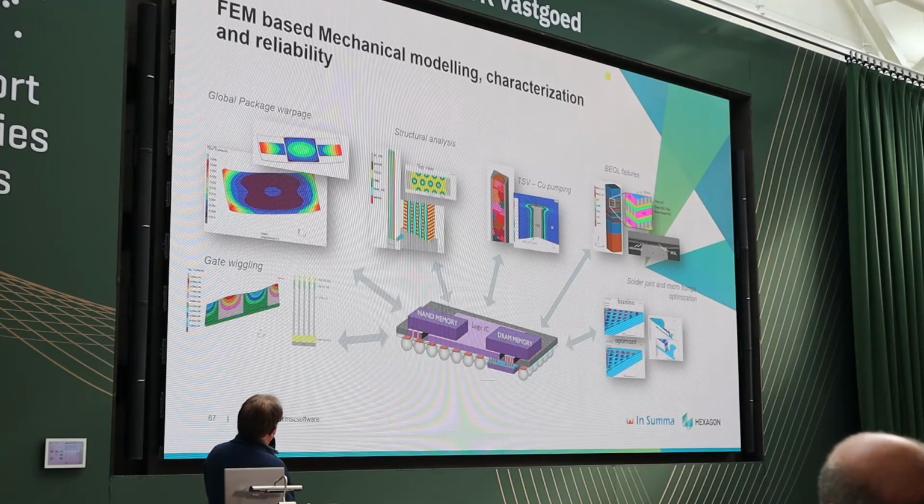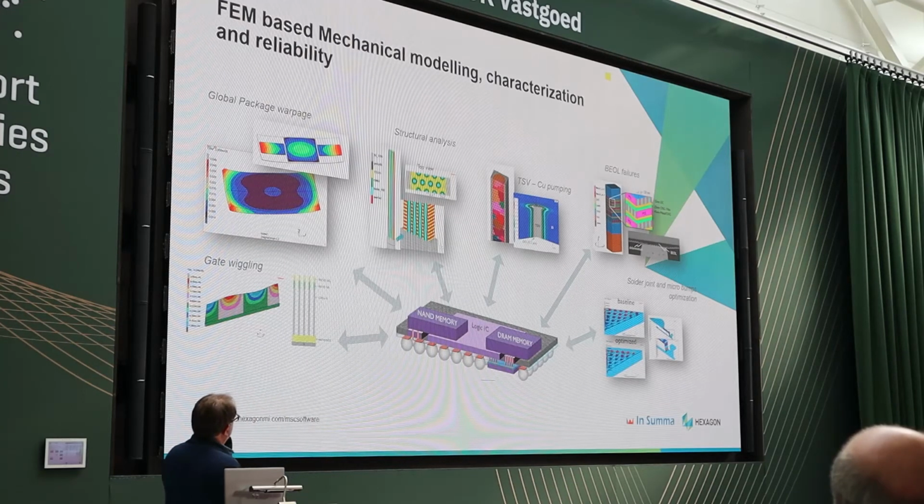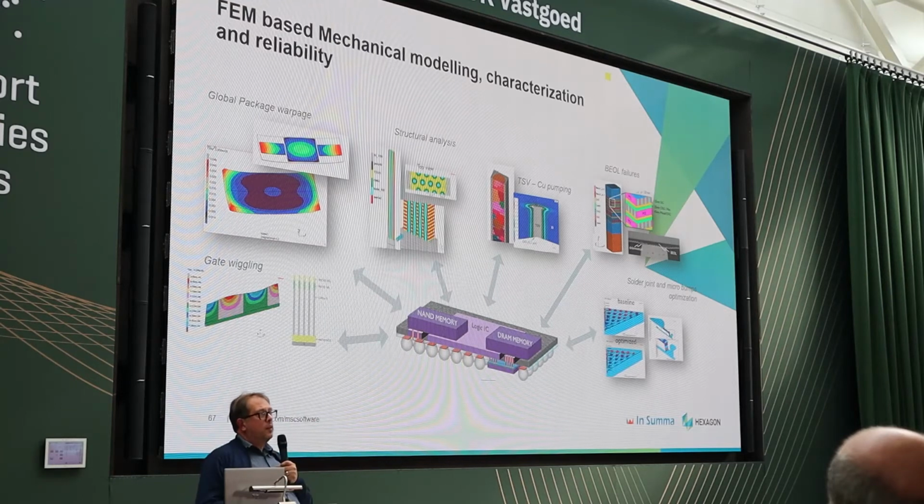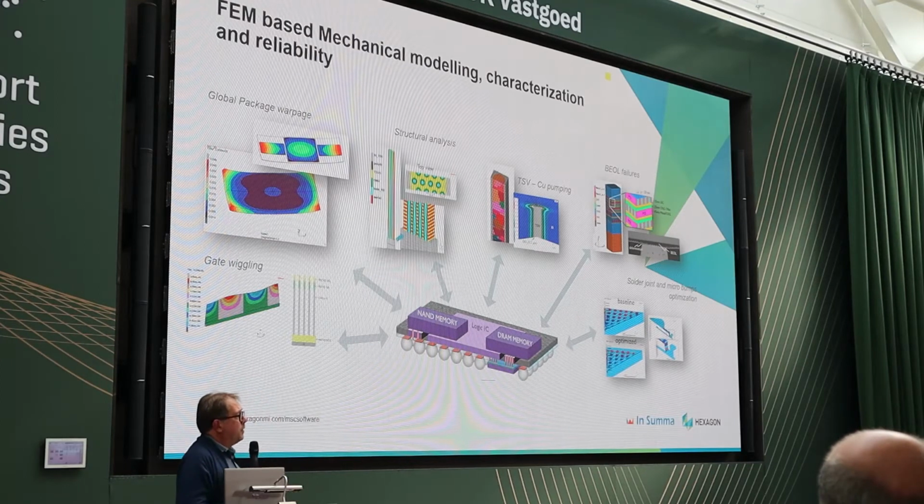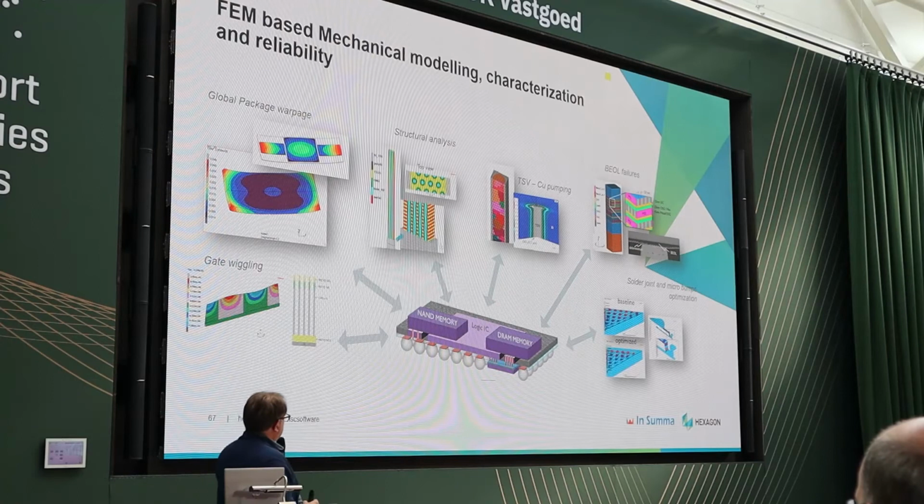Also looking at the microbumps, another example where the stresses can be an issue. And at the large component level, because you are mixing a lot of different materials that are also quite thin, you can have warpage and large bending, which is not allowed. A lot of studies have been done on such structures, and it's all done not in one simulation model, of course, but it's all the same research that has been performed.